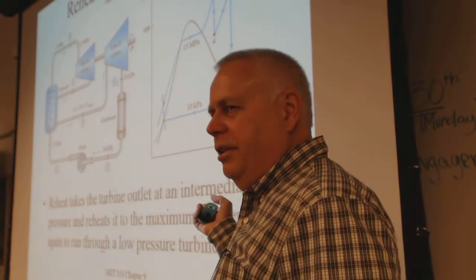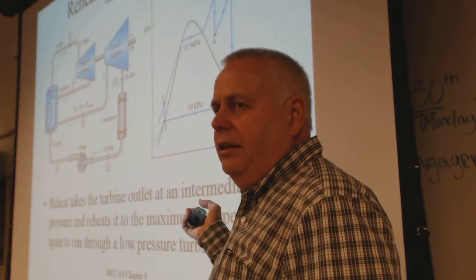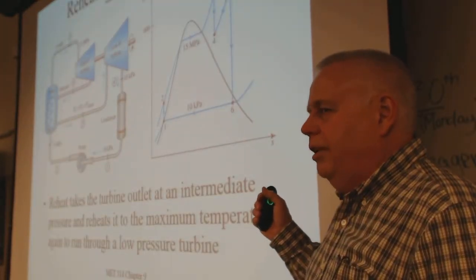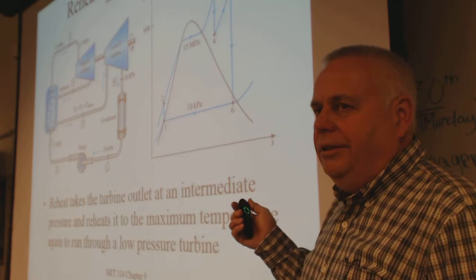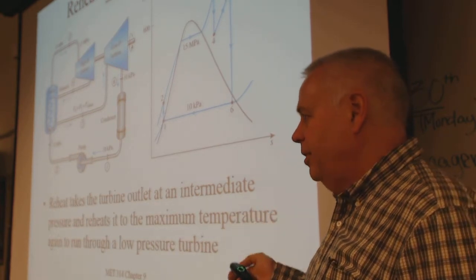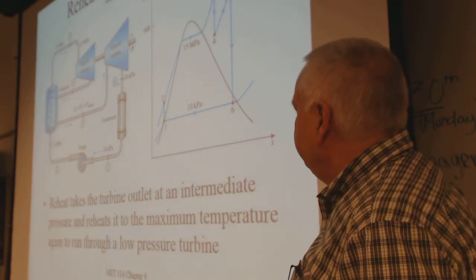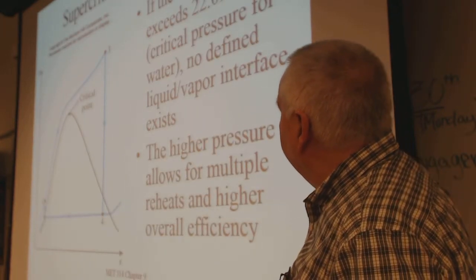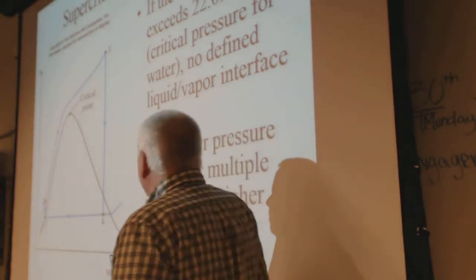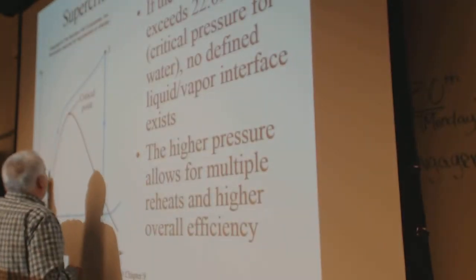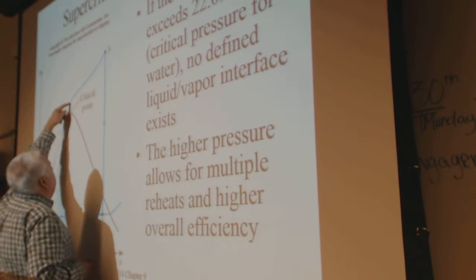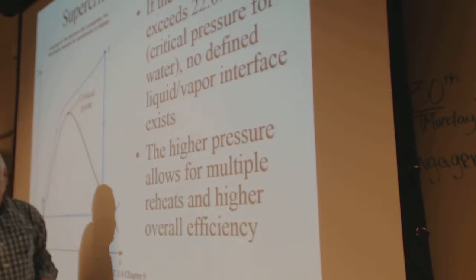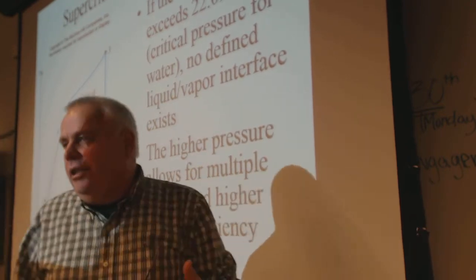So you can improve the cycle efficiency doing that. Our example said like 26% or something like that. I think that some of the state-of-the-art coal-fired power plants might get up to like 42% efficiency, which is about as good as you get. So there's an example. And typically, at this high pressure, you can't go to a super high temperature, so you go up to whatever temperature and down, and then do like 2 reheat cycles.